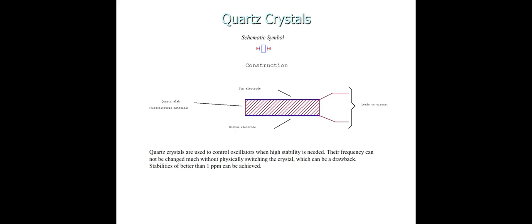Like a tuning fork, a crystal has both a mass and a resistance to bending, or elasticity. So by cutting the crystal to precise dimensions, we can achieve a precise frequency. The smaller the size of the quartz slab, the higher the frequency we can obtain, and crystals can be made to vibrate in a fundamental mode up to around 20 megahertz.